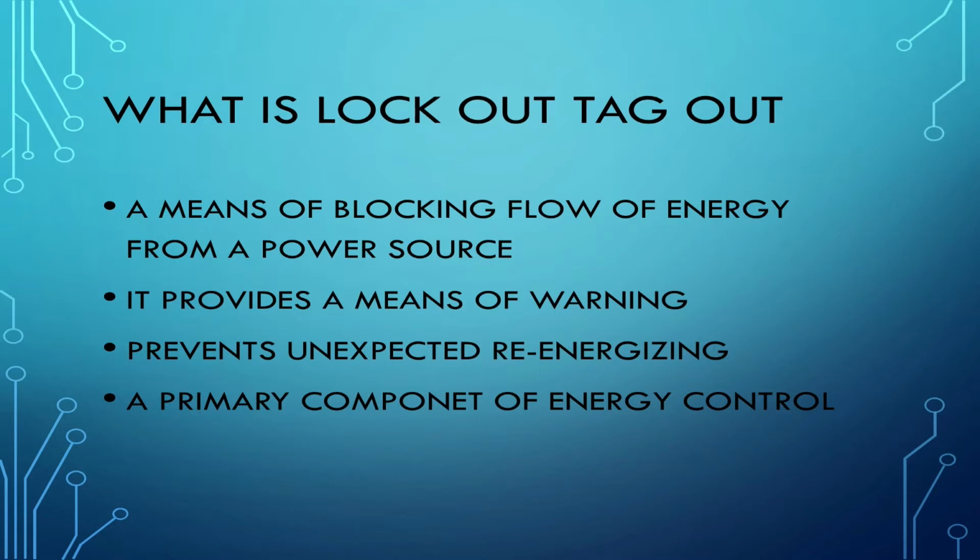electricity. It can be something that's tagged for an abnormality, something that is not reflected on your map system. Anything from normal opens to switches to a breaker bypass. All these items need to have a tag on them. All these items need to transfer information of what's going on, and if nothing else, just gets us thinking about what we need to do, what could possibly be different, what's abnormal, and who do we need to talk to find out exactly what's going on.